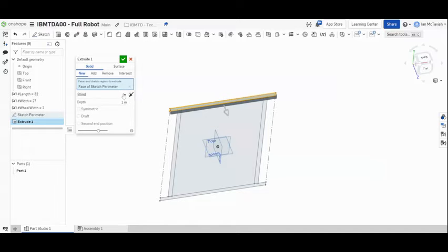And when you extrude, you have some options. You can create a new object. You can add if you already have an object, which we don't. You could remove. So let's say I had a rectangle and then I put a circle on the sketch. I could remove where the circle is, and an intersection. So an object that's created from 2 separate objects that intersect.